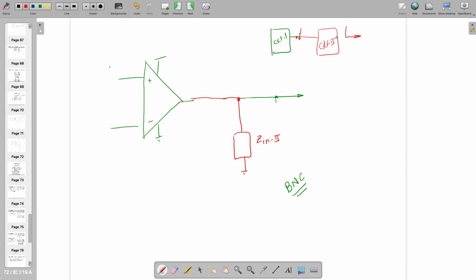So basically, this impedance arrangement that we are making is to nullify the loading effect. Actually, to mimic the loading effect. To mimic the loading, yeah, because that is the real situation. Sometimes, if you connect, let's say, a motor at the output, the motor's input impedance is actually very low. If I connect something like 10 ohm or 20 ohm here, the output, which earlier you were expecting to be 5 volt, after connecting this is 0.5 volt or something like that. So you know the situation.